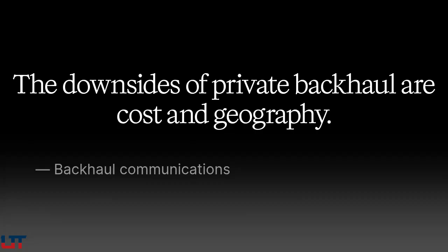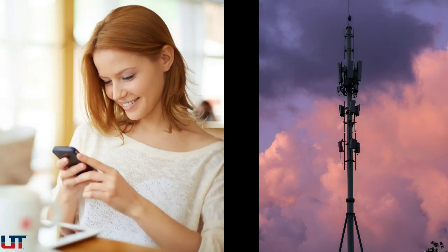For remote sites where private infrastructure isn't practical, geographically isolated pump stations, distributed pipeline valve sites, weather monitoring stations, public communication infrastructure fills the gap. Cellular, LTE, and 5G connectivity is cost-effective, widely available, and increasingly reliable. It's the default choice for remote RTU connectivity in most new deployments where private infrastructure doesn't exist. The critical security requirement is that any cellular path must terminate at the central SCADA site through a VPN tunnel.